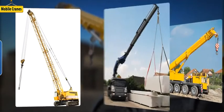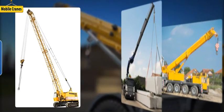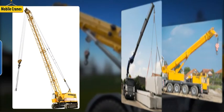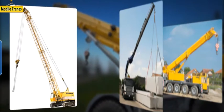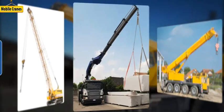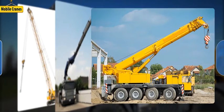A crawler crane consists of a rotating superstructure equipped with a power plant, operating machinery, and a boom, all mounted on a vehicle equipped with crawler treads, and is useful in rough terrain environments and in different weather conditions. Truck cranes have the same basic equipment, but are mounted on an automotive truck and can lift varying sizes depending on the size of the vehicle. Wheel-mounted cranes also contain similar equipment, but are mounted on a base or platform equipped with rubber wheels for travel. Wheel-mounted cranes often look similar to truck cranes, but they're generally much larger, usually with 12 or more wheels.